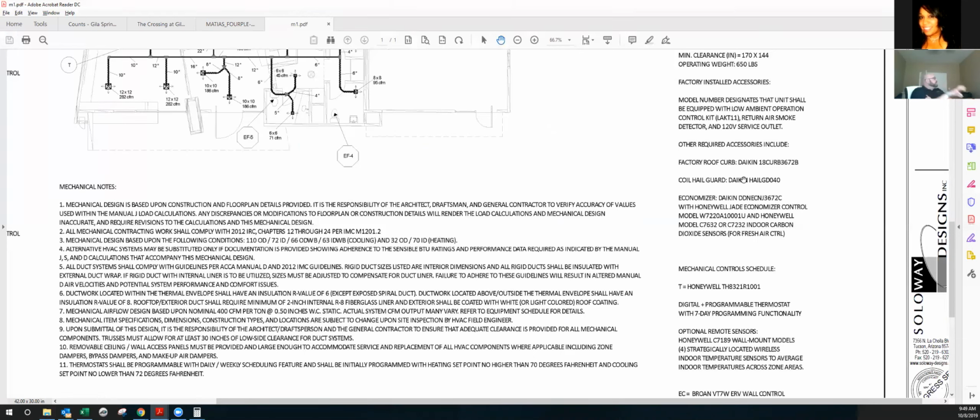Whether they do it through our equipment or there's a second piece of equipment that they use to bring in makeup air. There's dedicated units that do that, or you have ERVs, energy recovering ventilators that can perform that function. So when I say it's required, a manual damper is not required and an economizer is not required necessarily, but they've either got to provide it some other way or they've got to get it from us. So an experienced TSM should be able to quote the equipment, select the appropriate curb or curb adapter, and then select the appropriate manual damper or economizer.